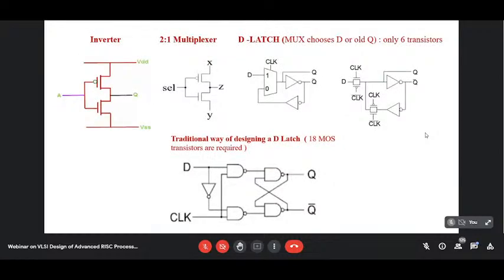So here, in fact, is the concept of hardware. Whatever we have discussed so far, we understood that we need registers, and for registers we need flip-flops, and the basic flip-flop, how the flip-flop can be designed. Now there are two concepts. Traditionally, we have learned that 4 NAND gates will be connected in this fashion, what is given at the bottom of this diagram. Now 4 NAND gates and 1 NOT gate give a complete D flip-flop.